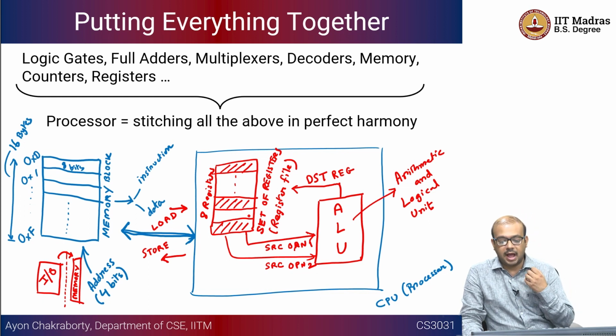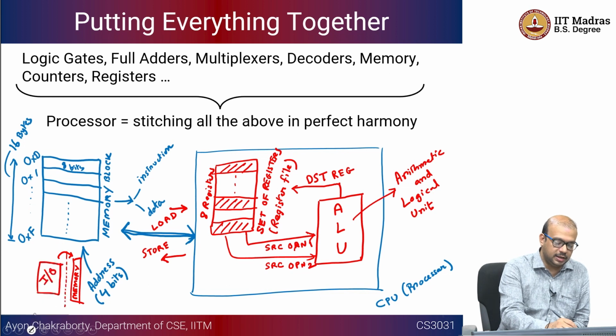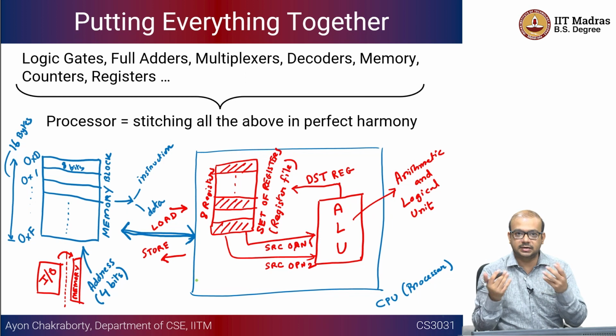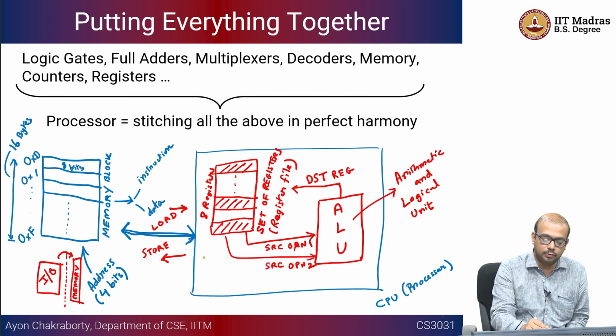So, if I want to have the instruction which explicitly specifies so much, I have to encode that information using the required number of bits, right. So, here I am basically telling source register 1, source register 2 and destination register. So, 3 registers. Each register takes 3 bits to be identified, right. So, if I have 3 such registers, I will require 3 into 3, 9 bits, right. So, let me write it here just to give you an idea about how the instruction is going to be encoded. So, here I have 2 to the power 3 equal to 8. So, 3 bits to identify a register.